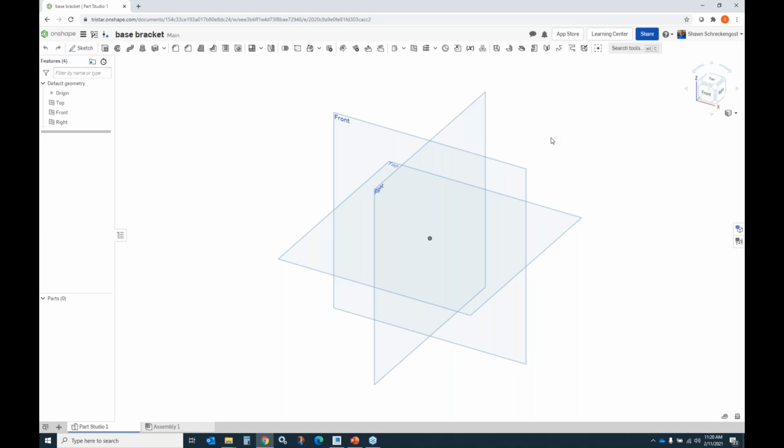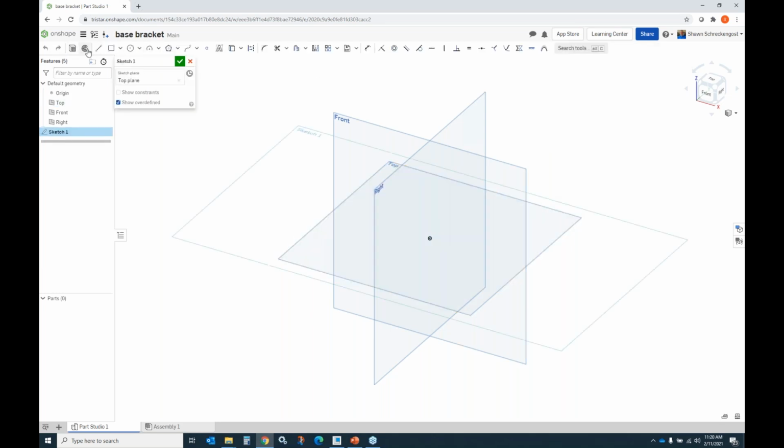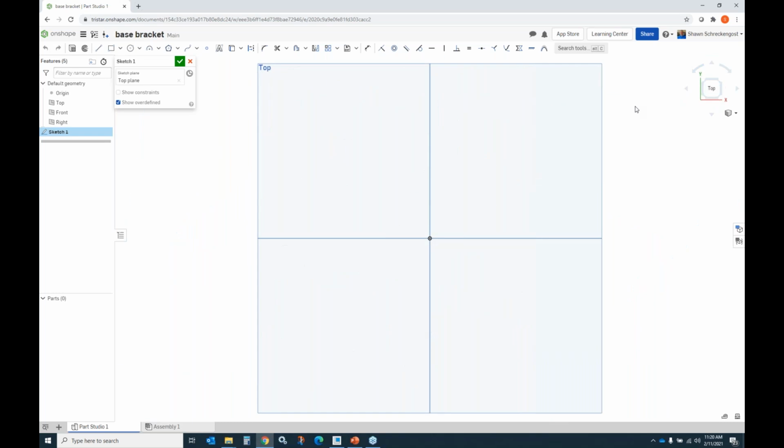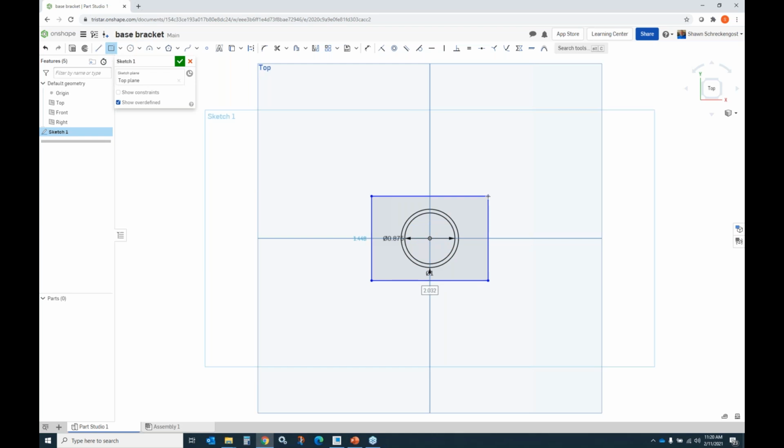How we would go about creating CAD parts in an Onshape document is I would be working in this part studio, and I may create a sketch on a plane, right? That sketch might include several types of sketch geometry. I might create a circle, and that circle might have a diameter of, say, 1. Maybe I have another circle with a diameter of 0.875. Maybe I create a center point rectangle, and it has 2 dimensions on that. I'm just sketching this out and entering the dimension values as I sketch it, right?